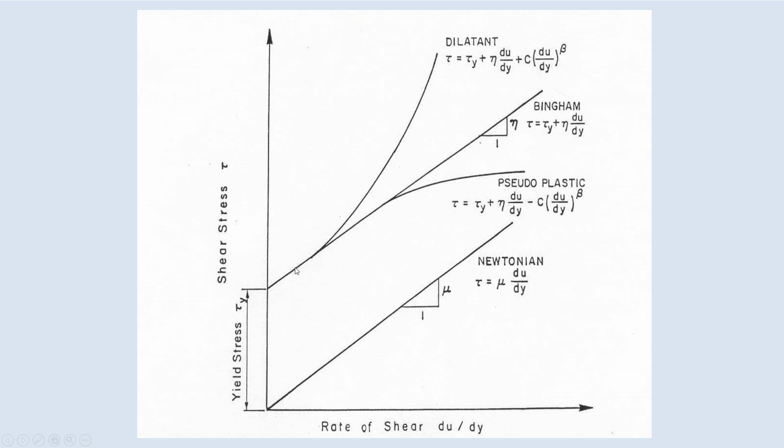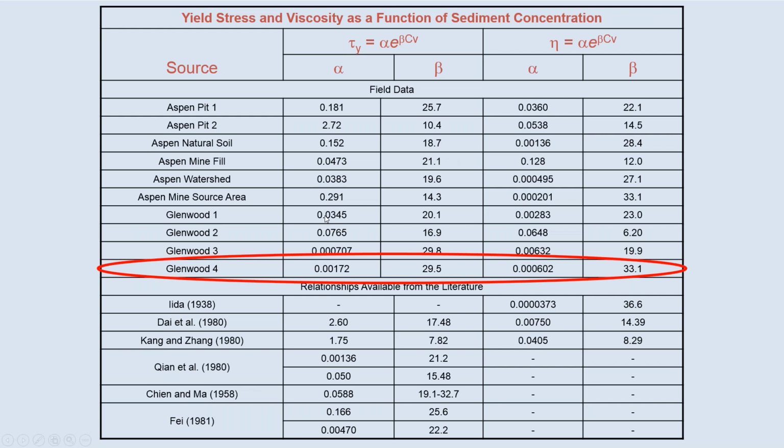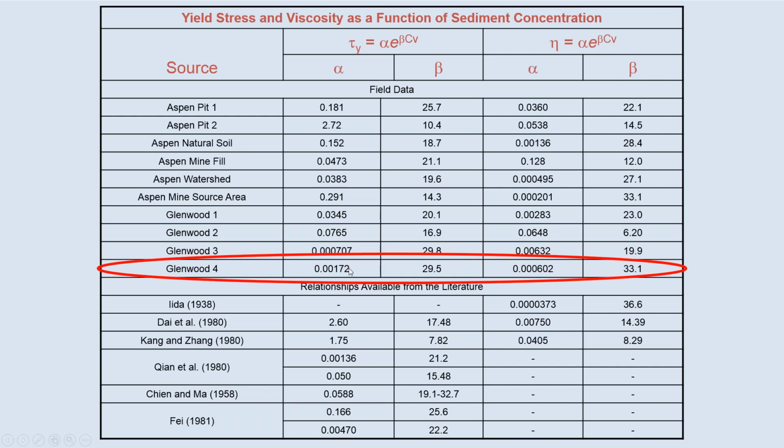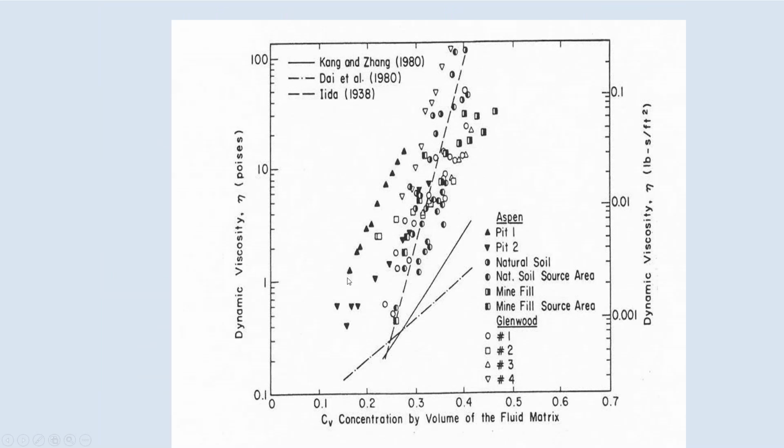So you'll have your rotational viscometer operating at one speed, and then you'll crank up the speed, measure the shear stress, and you'll get these points on this curve that will lead to one point. So it'll take you like 10 measurements in order to get one of these points. So each one of these curves represents about 100 data points.